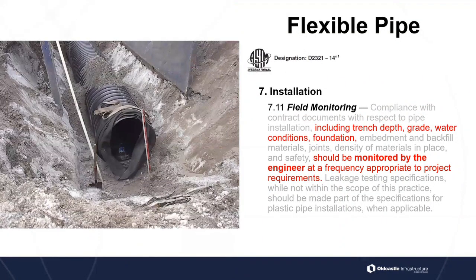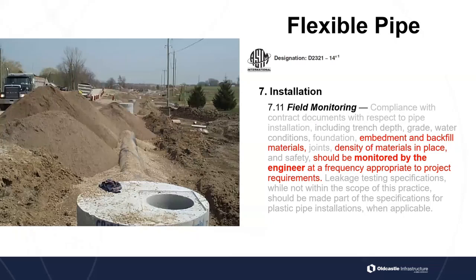Is that pipe, that end there, is that being installed correctly with the trench boxes? Is it covered up correctly to ensure that something doesn't get in there? Is it anchored correctly? It looks like you've got a trench box there on the side and then nothing opening up there. So there's obviously shovels down there, so someone's been down there. So these are issues that we need to take into account when we're engineers, and looking at all of these different things.